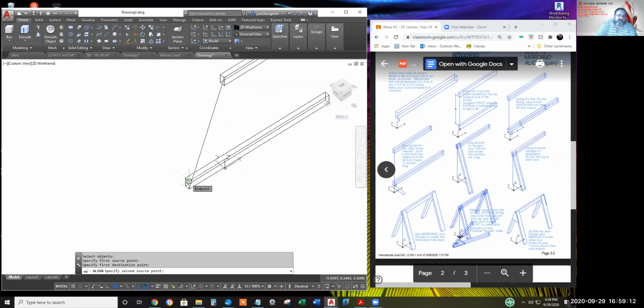They still work, but they disappear. I'll attach a second bungee cord, slightly weaker, to this corner. Now I want it to appear about right here, but that ain't an O-snap. So I could type NEA to invoke a near point O-snap override. Instead, I'm going to slide all the way up an O-snap on the midpoint.